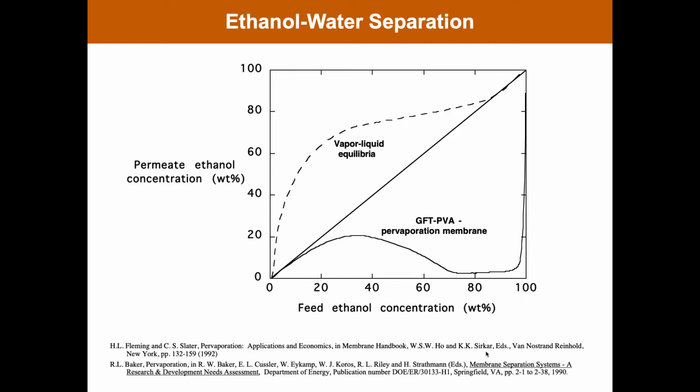And so if you go to one of these plants, you see this large amount of low content alcohol coming into two distillation columns, and that reduces the volume of the required feed enormously by about half, but increases the alcohol concentration quite a bit. And so those two initial distillation columns then feed a single second stage distillation column that brings the concentration of alcohol up into the region of the azeotrope.